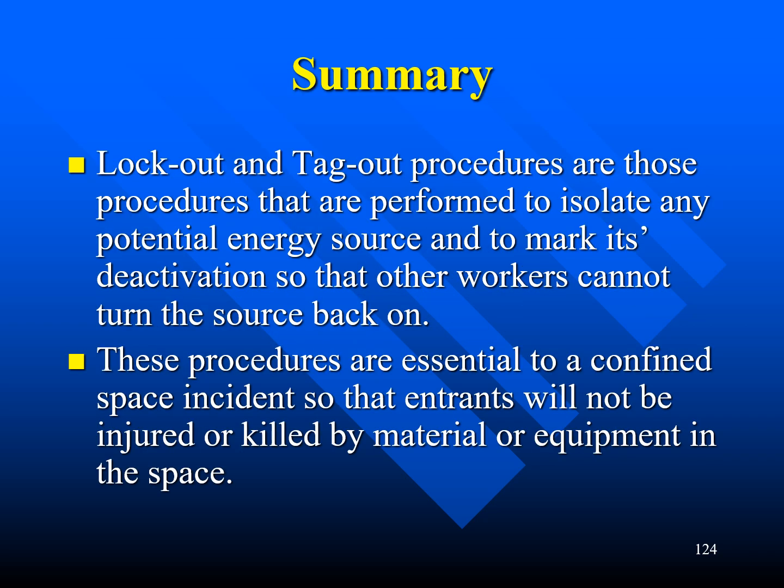Let's summarize this lesson, class. Lockout tagout procedures are those procedures that are performed to isolate any potential energy source and to mark its deactivation so that other workers cannot turn the source back on. These procedures are essential to a confined space incident so that the entrants will not be injured or killed by material or equipment in the space.